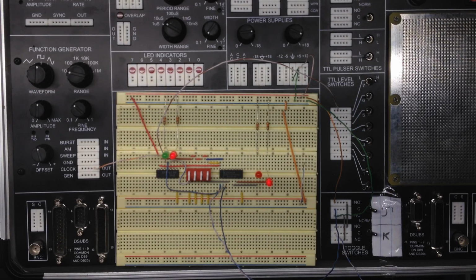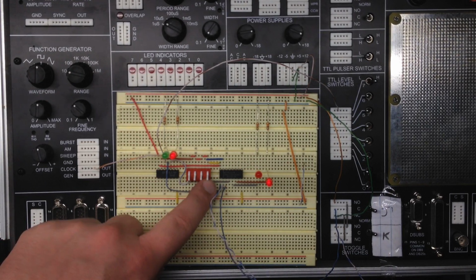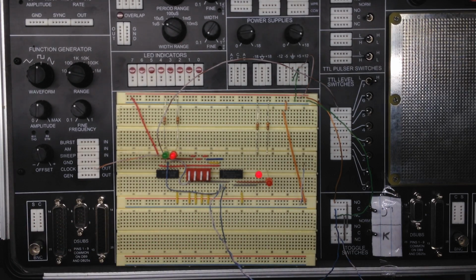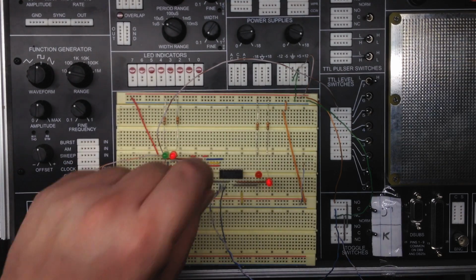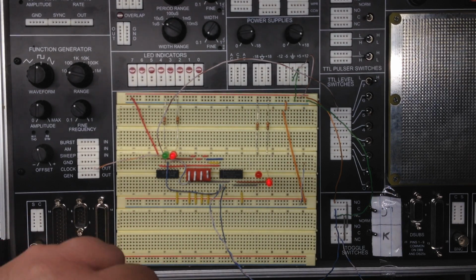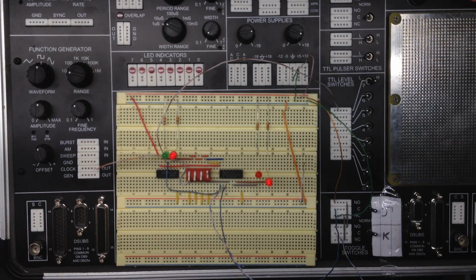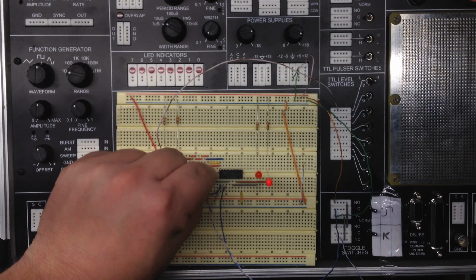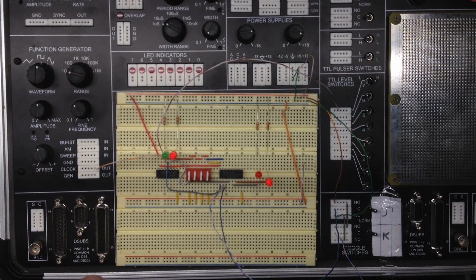So we're going to start by setting the preset, which is the switch to the right. We're going to set it to low. When this happens and the clear is on high, then Q should be high and Q naught should be low. So we see an immediate change in the outputs of Q and Q naught. Q is currently set at high, Q naught is set at low. If we turn this back off, we should go back to a toggle action.